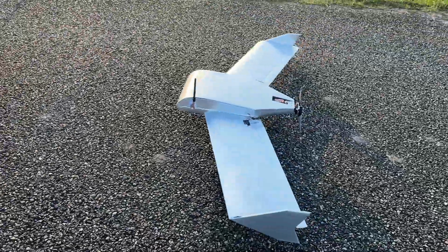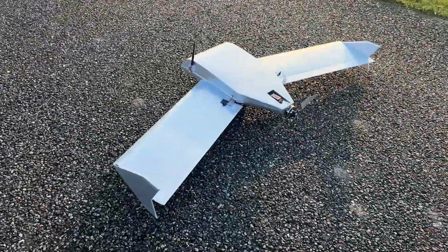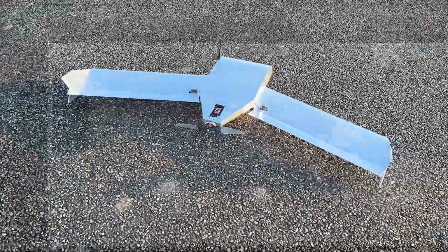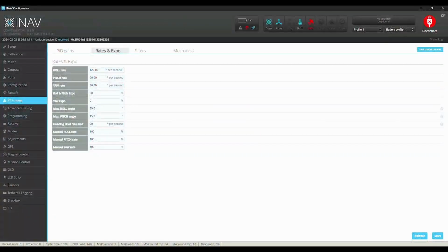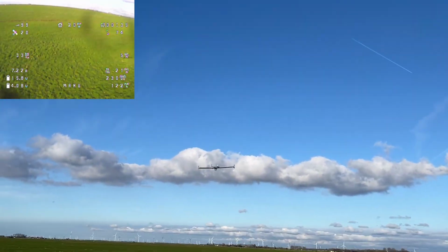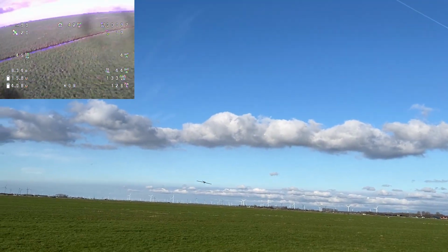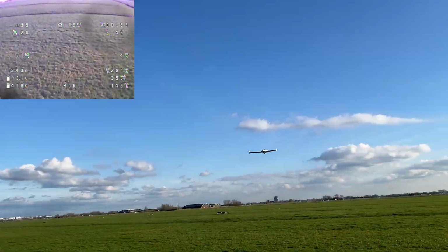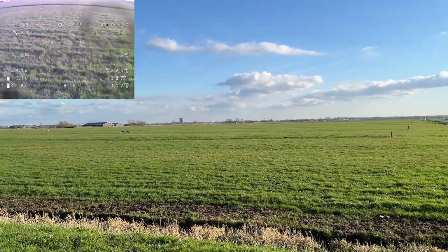That creates its own stabilizing force. But even with that, a flying wing needs constant active stabilization. The flight controller is always making micro adjustments. If the computers fail, it falls out of the sky. That's why you don't see flying wings in consumer drones. Too risky. They're mostly research drones, military applications, and experimental aircraft. They are proof that aerodynamic efficiency is possible, but for most applications they are overkill and too complex.